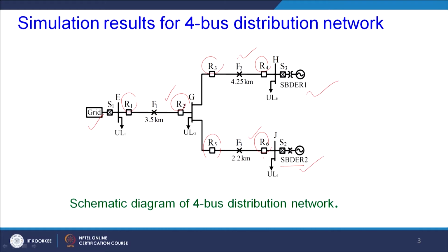In today's digital relaying platform, if we are using the directional overcurrent relay, we are not going to incur any extra cost, because almost all the relays are multifunctional in nature. We can use the relay as a directional overcurrent relay, or only as an overcurrent relay, or only as a directional relay, distance relay, or differential relay. That is one of the advantages of the digital relaying platform.